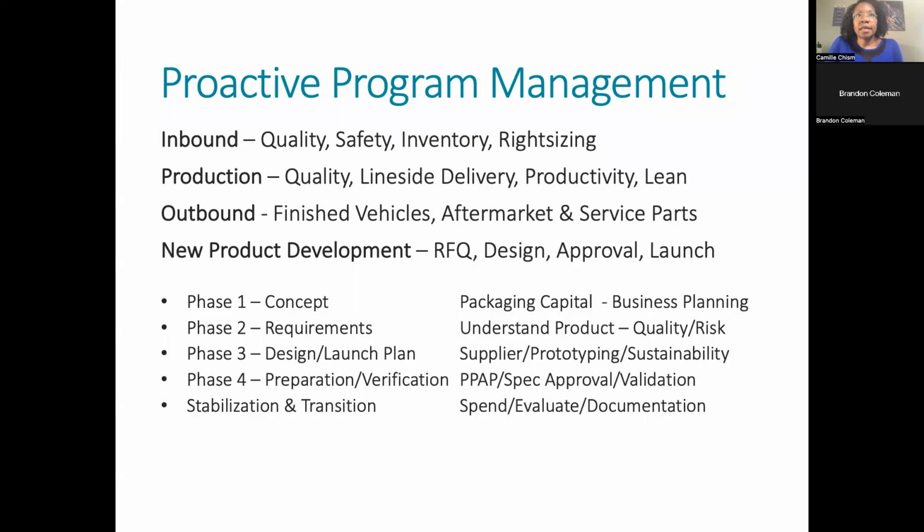Things like right sizing. Right sizing is the process of determining how many parts go in a pack. So you might come up with a package that will hold 8 products, but maybe those parts are hitting each other and scratching each other. So maybe they need to be separated. Can you separate them with material that protects them, or do you actually need to separate the parts even further? And now you end up with maybe fewer in the pack. Normally, right sizing is a process of looking at how we can get more parts in a pack.